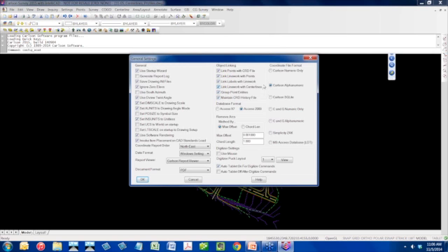So with the new IntelliCAD, with the new release, they've built in all this linking, and it's going to be important. For instance, we're going to link the line work in the drawing with centerlines. So when we station our centerlines, if we change the beginning station, which I'm going to show you, it's going to update in the drawing for us. So that is an important thing to go in and start with.